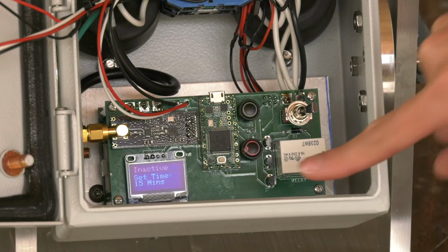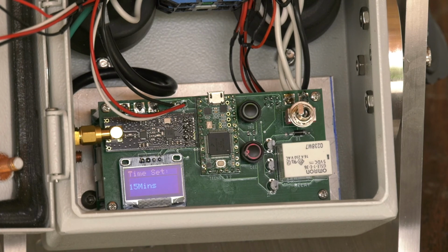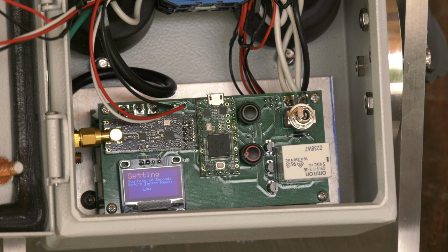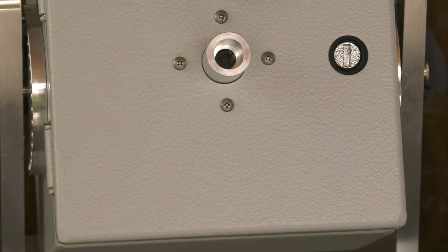The initial default time is set at 15 minutes and can be adjusted by intervals of 5 minutes, with 5 minutes being the minimum set time and 60 minutes being the maximum set time. The time is saved internally for power cycle save mode. Once the assigned period of time ends, the timer will cue the relay to shut off the power and reactivate the PIR sensor for motion input.